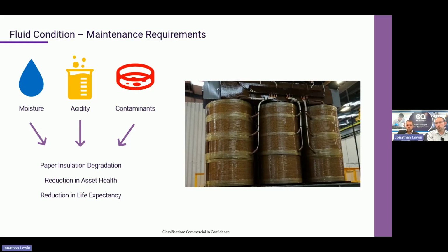So all these factors, whether that's high moisture, high acidity, or contaminants within your asset, will accelerate the degradation of your solid insulation, thus reducing the expected lifespan of that asset. The idea is you undertake remedial action to then prevent that accelerated degradation from occurring.